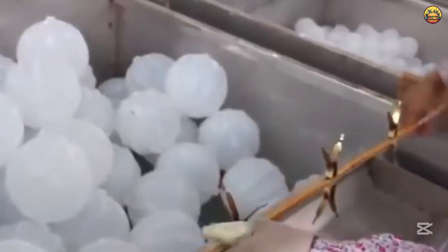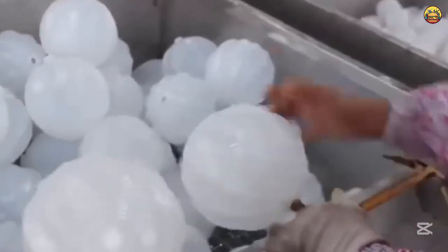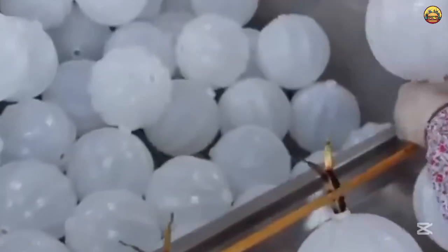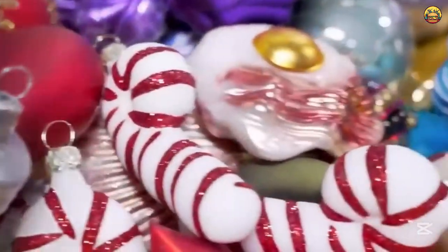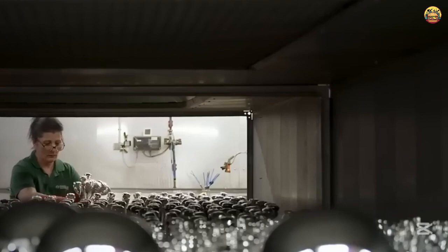Once tested, the molds are sent to an injection molding machine, where liquid plastic fills the mold. After the plastic cools, the mold is split into two parts, and the completed pieces of the ornament, if not made in a single piece, are assembled together. Handling heated plastic isn't exactly pleasant, but the results are absolutely worth it.